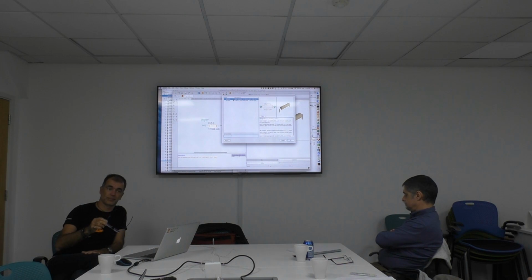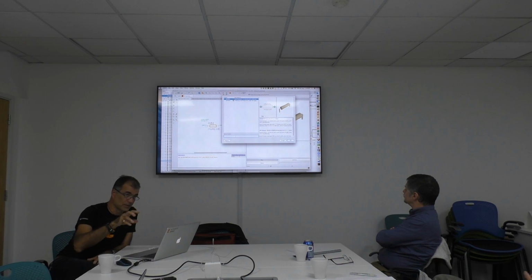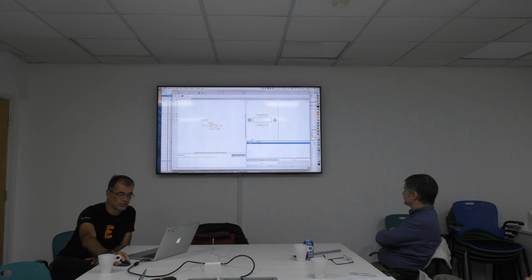We have the LM555D and the N. N is typical for DIL, D for SMD. You have to name it here. I leave it as it is because I decide to only have one in this case. Sometimes in the resistor library, you see the package variant, the number of the package, it's 02 or 4 or something like this, so this could be the variant name here. Okay, there it is.